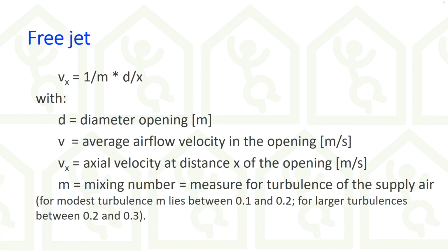The location where the air leaves the space has almost no effect on the airflow pattern. This is because during the exhaust of the air, the kinetic energy occurs in the return duct, while the airflow to the hole takes place from all directions in the space. The air velocity of the supply to the hole decreases in principle quadratically with the distance to the hole.